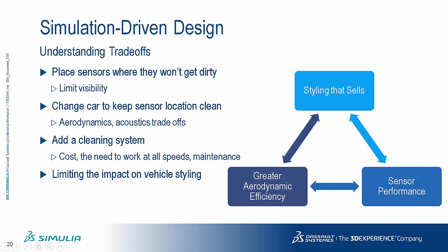So we understand that if we change a certain corner on the vehicle, the soiling line is going to move, but that means that we need to have more sprayers, and then that would maybe mean that you have more weight to carry around for spray. And that might not be a good trade-off. Or, for example, you could change your braking system to improve your cooling, so introducing more airflow onto your brake, but you might also be putting more water onto it and reducing your braking efficiency.